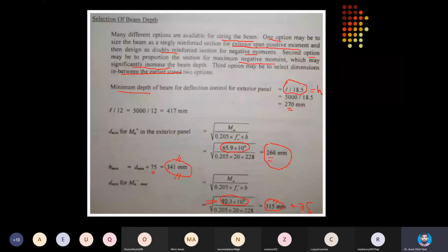So how much portion of the slab which is cast monolithic with the beam will become integral part of the T-beam. So this BF decision about how much is the width of the flange is very important in order to fix the geometry of the T-beam in monolithic construction.